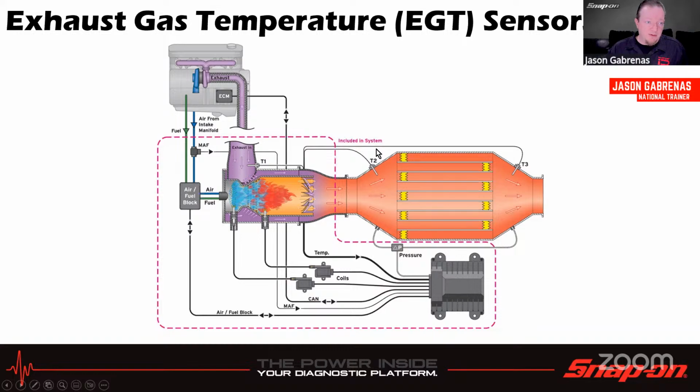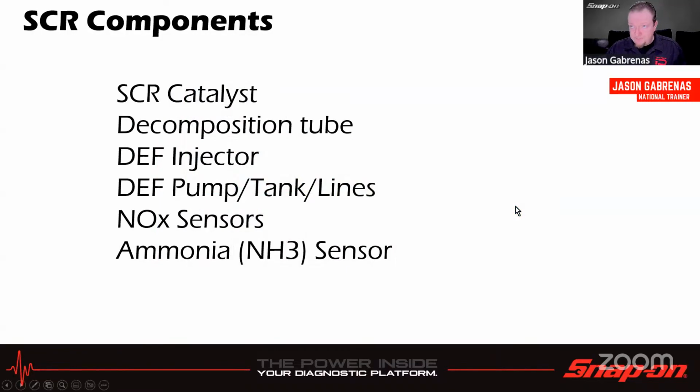Another one needs to be between the DOC and the DPF, to see if the catalyst lights when dosed. It's also used for comparison to the DPF outlet to see if it's burning soot. And then the DPF outlet is there to see if the DPF got hot during a regen, and also to know when the regen is over. The temp will drop off once all the soot is burned. So there you go. The computer needs to know what's going on in those 3 spots, at least.